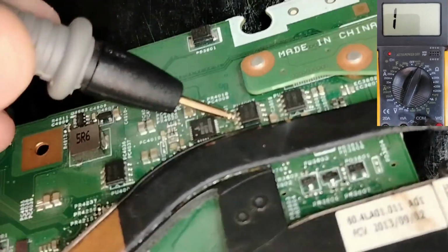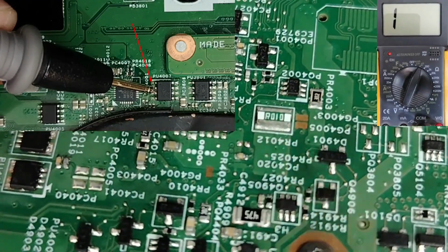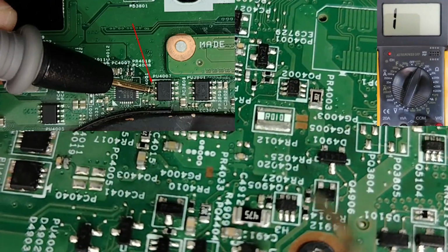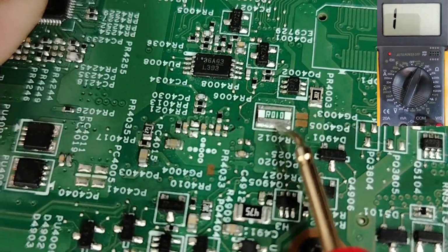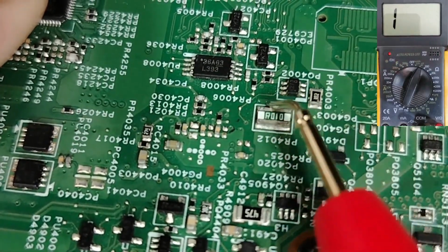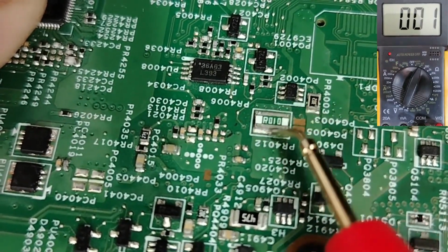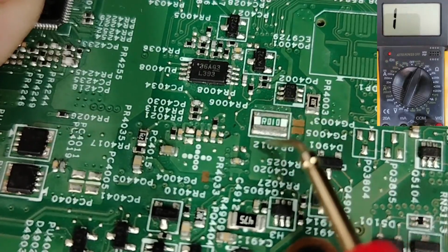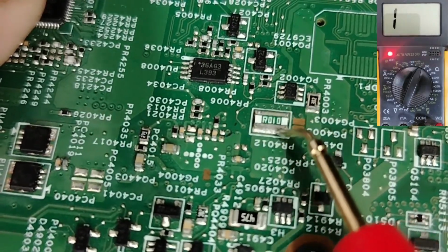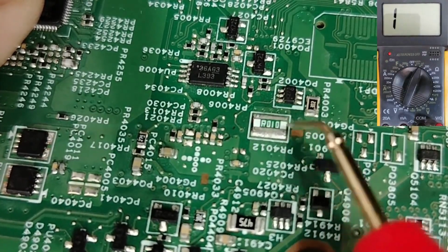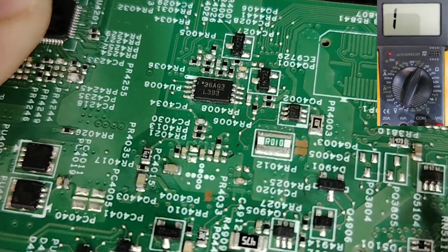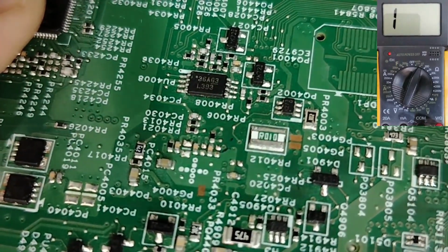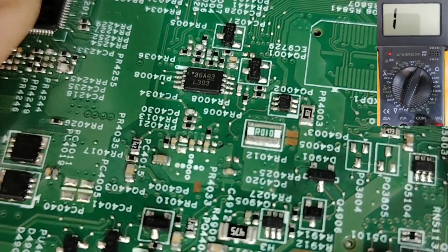Let's go to the current sense resistor in the back. So guys, here we have the current sense resistor, with the black probe on the MOSFET. Let's check. Do you see? Continuity, a direct connection on this side and also on this side, on both sides. Why? Because the resistance here is 1 ohm. So if this resistor is damaged, if it is open, the 19 volt will not pass and will not be distributed to all circuits in the motherboard, and then the motherboard will be a dead motherboard.